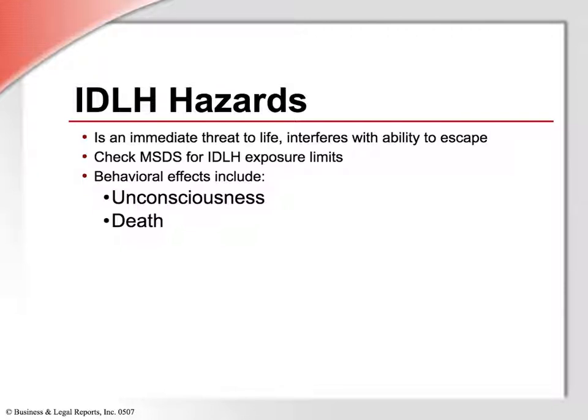The IDLH, immediately dangerous to life or health, means any condition that poses an immediate or delayed threat to life, that would cause irreversible adverse health effects, or would interfere with the individual's ability to escape unaided from a permit-required confined space. All confined spaces should be considered IDLH until proven otherwise.